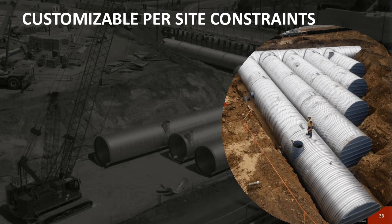So you can see here some of the fabrications. You've got an inline riser that the gentleman is standing next to, replacing a concrete manhole structure, which might be used on other systems. And then you can see the fabricated bulkheads with the reinforcement attached already to them. So when it delivers out to the job site, you can set those pieces with the fabrications and the bulkheads on them, just like you would any other piece. So it does not slow down the installation process at all.